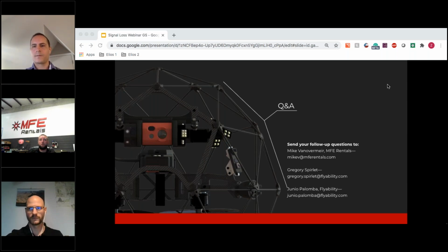So in relation to the other person, are you standing 10 feet away from them, open line of sight? Are you standing 10 feet away from them with a concrete wall in between you? Different things like that. That's honestly one of the hardest things we have an issue with when we get asked the question of, well, how far can we go, or how far is the signal going to broadcast? That's completely dependent on a lot of outside factors. So it's very tough to answer that. But again, relative to each other, I would say about 30 feet. That's, at least to me, the comfort area I would go with, and that's open line of sight. But if I had something in between us, that signal strength is going to be cut down pretty dramatically.